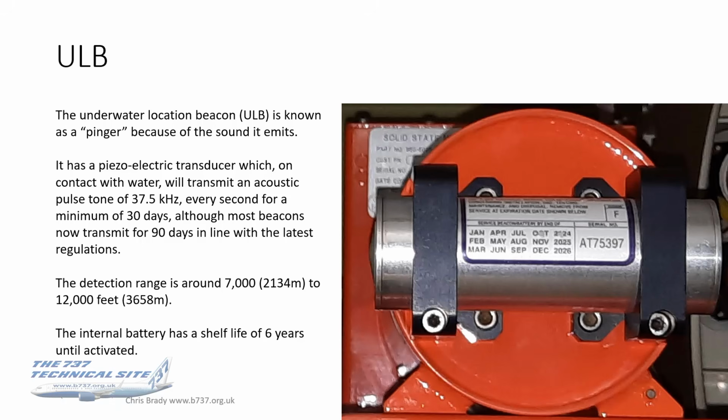The other component which is common to both the FDR and the CVR is the underwater locator beacon. It's known as a pinger because that's the sound it makes if you ever hear it. The way this works is it's got a piezoelectric transducer, which when it makes contact with the water, activates and transmits this acoustic pulse tone, which we hear, of 37.5 kilohertz once a second for a minimum of 90 days.